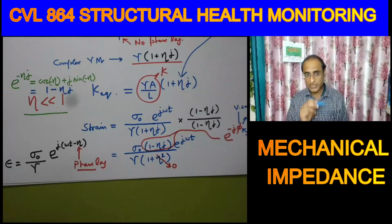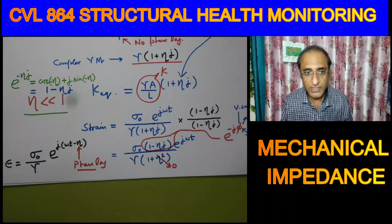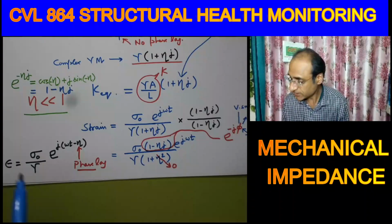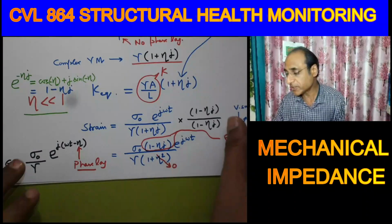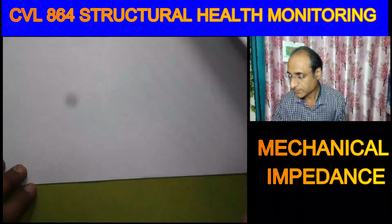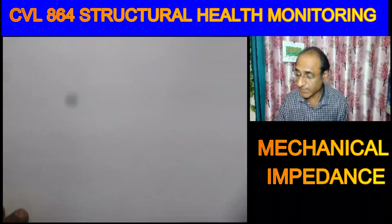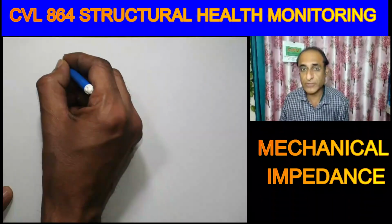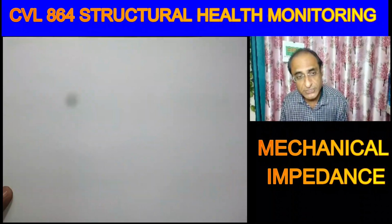So basically complex Young's modulus is, we always say that the dynamic Young's modulus is higher than the static Young's modulus. What is the reason? The main component is damping, and of course there are inertial effects also.